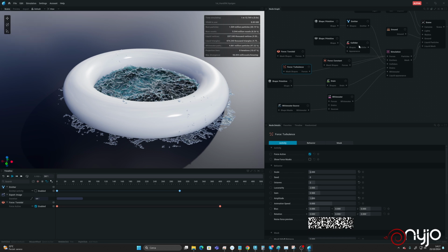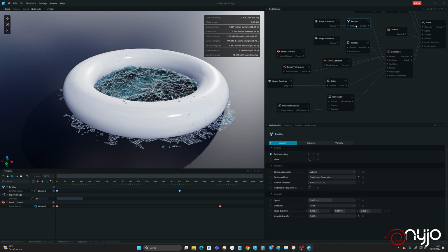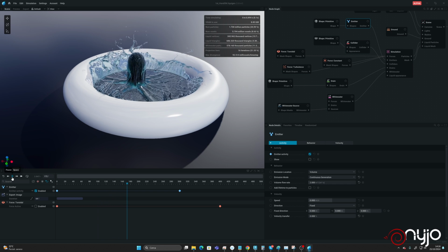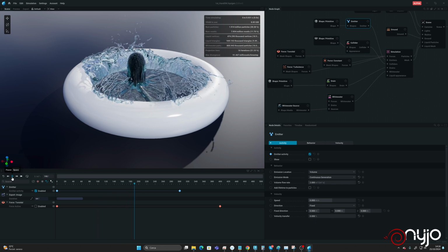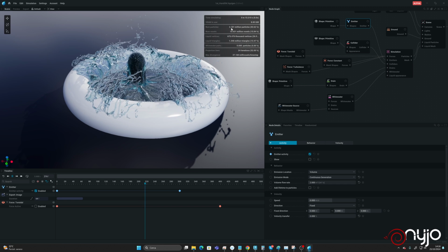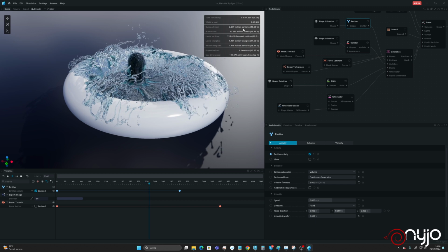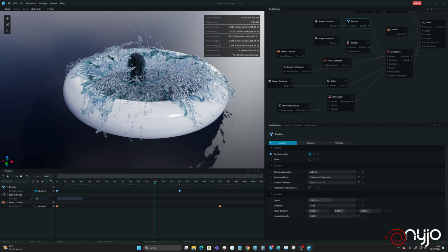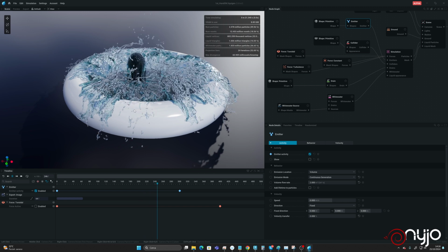And then to have more particles, we can go in the emitter and say that it's emitting 2 meters in the flow rate. So you see that we have more particles. With more particles, obviously, we have something that is more detailed than before. We are using a higher number of particles, so we have to see if we reach the maximum number of particles we can use.